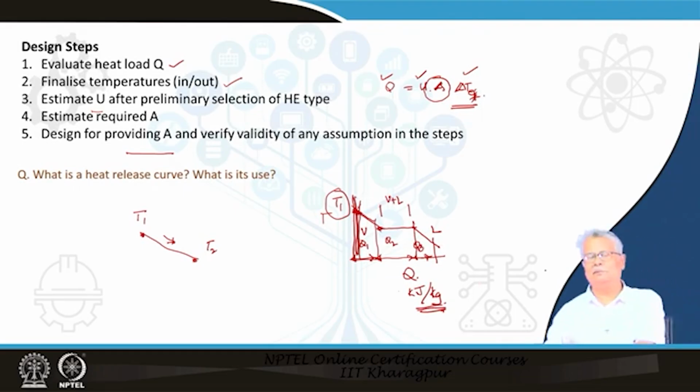This clearly tells you something. It makes your calculations much easier for designing, as you consider in such heat exchangers 3 different zones of heat transfer, and then you go for your design. I have just told you this because you may love to have this in hand before you start your design work, particularly if you are going to have phase changes.